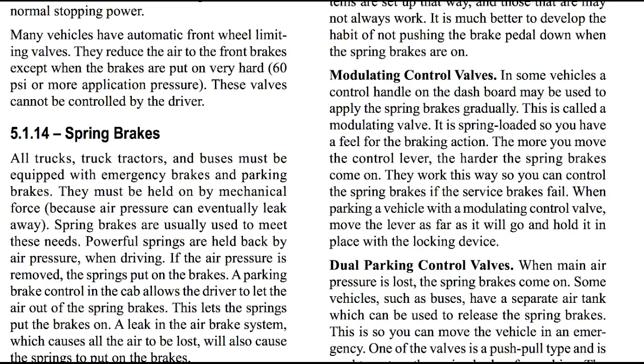When parking a vehicle with a modulating control valve, move the lever as far as it will go and hold it in place with the locking device.